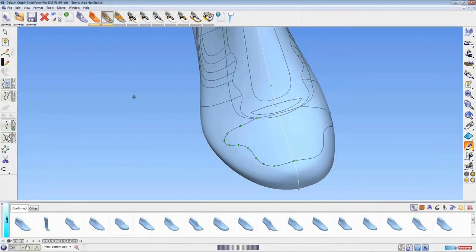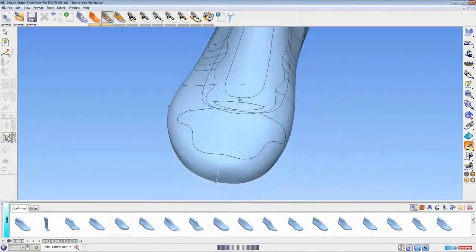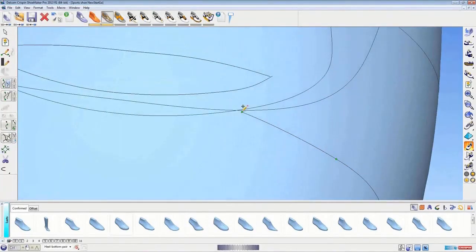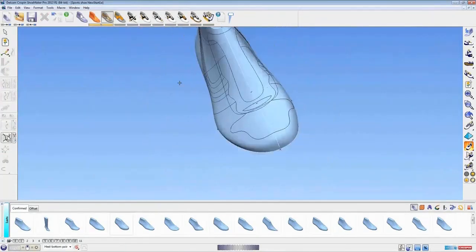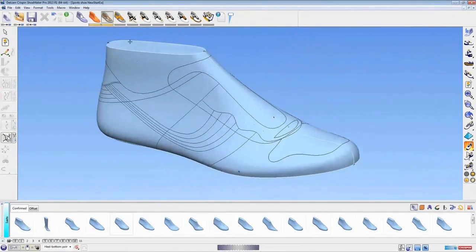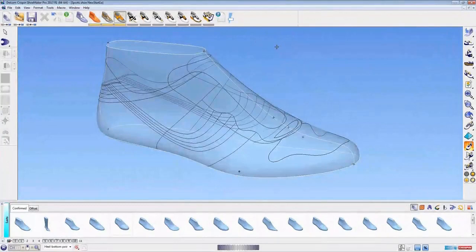Now the design line we sketched at the front, I need a copy of that, so I'm going to make an unlinked mirror at the front. And I'm just going to zoom in at the end point and just dynamically edit that point to make sure it's in the correct location. For the next element, which is piece creation.